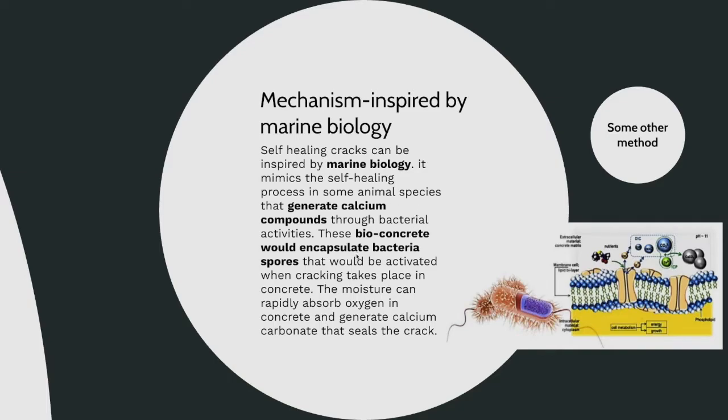So for this bioconcrete in real life, we can encapsulate the bacteria inside maybe some core-shell structures, and they will be activated when they are ruptured or when the cracking happens. So it's similar to the capsule-based self-healing materials, but the inside is bacteria. These bacteria will work when they are absorbing the oxygen, and they will generate the calcium carbonate.